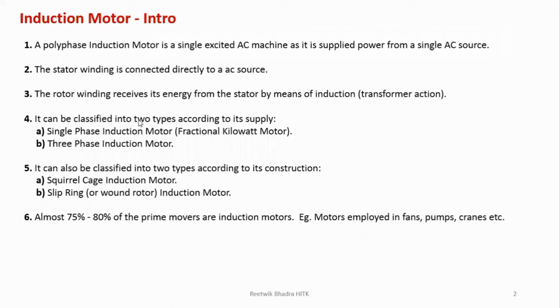In industries there are three phase induction motors. So basically what we have understood from here is that this induction motor has to be given a three phase supply. It has one static part known as the stator, and the rotating part known as the rotor. It works on the principle of transformer action only, that is mutual induction. And it is of two types according to the supply: single phase and three phase, and according to the rotor construction: squirrel cage and slip ring motor.